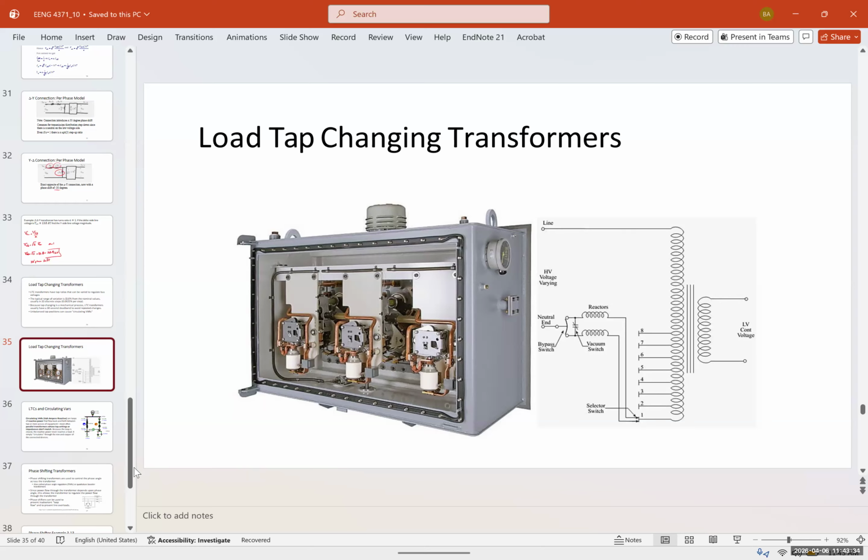Now, another thing to keep in mind, this is usually done automatically, and it's a three-phase system. So you have a three-phase Y connection, and you do it for each phase. Usually if it's a balanced system, it's treated as a single phase and you're changing it. Some systems are able to individually connect those transformers. Now, again, it has 33 steps. I'm sorry, each step is 0.0625%, and it does a 10% change.